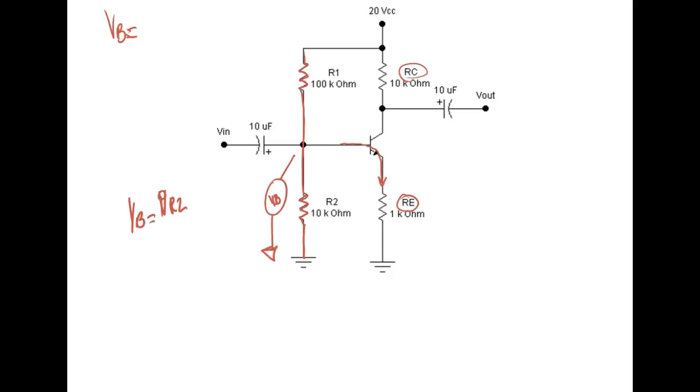The voltage divider formula is the easiest to use here. Y'all know the voltage divider formula. So what's the voltage divider formula? It's the applied voltage, 20, times the ratio of these two resistors, which would be 10K divided by 100K, which would be 1/10, because the K cancels and the two zeros drop. So this is going to drop 1/10 of the voltage.